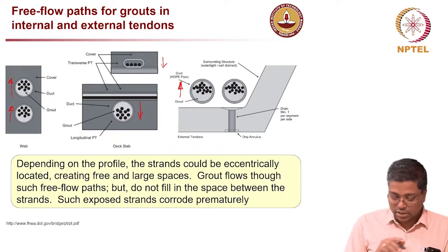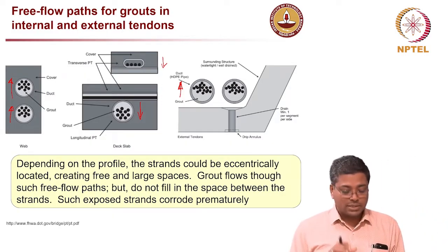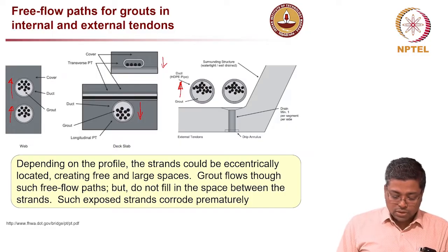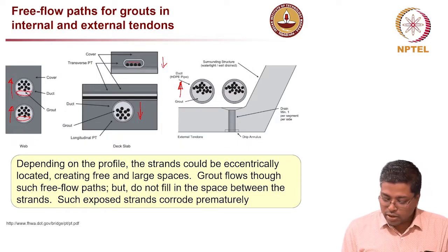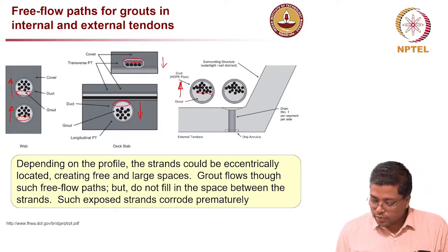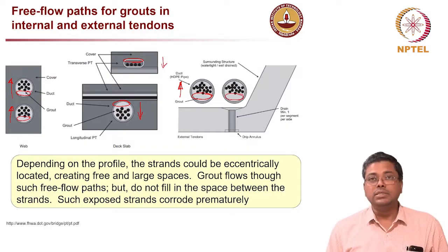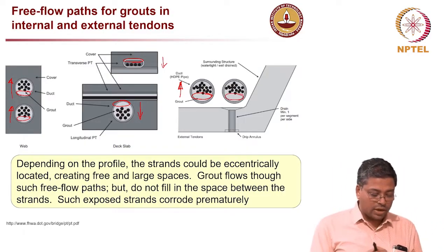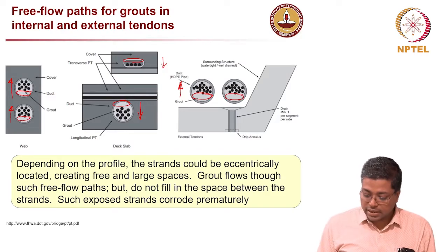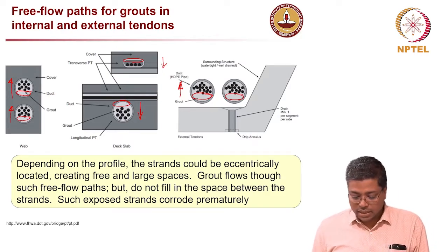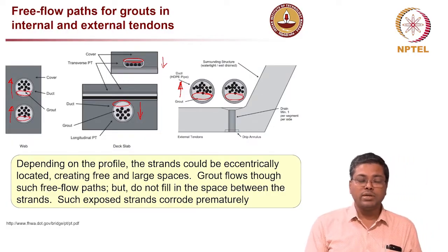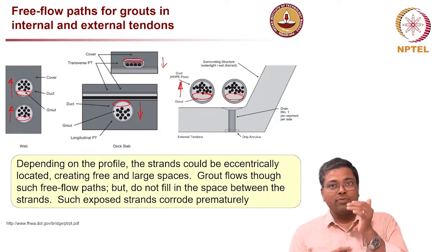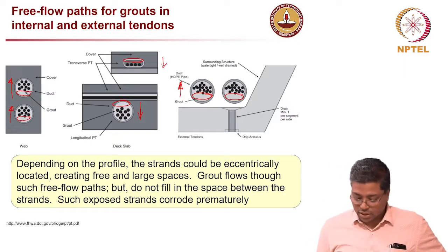So it's not necessary that the strands will always be at the center. Because of this, there is some region here, as I'm drawing, which is a less congested region, and the grout which you flow goes through that region and reaches the other end. And then people generally conclude that if the grout is pumped from one end of the tendon and reaches the other end, it is completely filled.